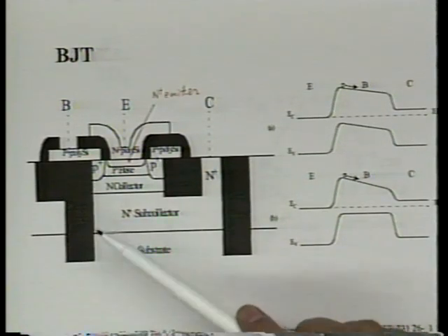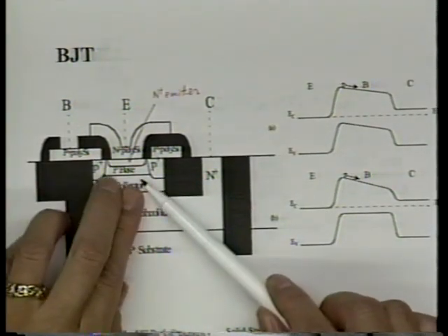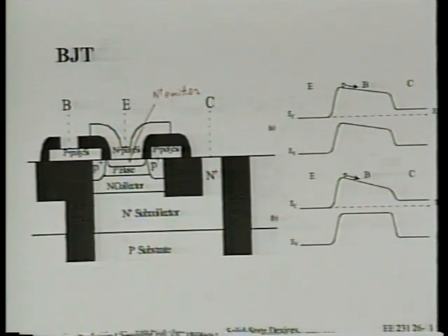Not only because we have a heavily doped N junction and quite heavily doped P junction, which make the base-collector junction breakdown voltage low, but also because of something we talked about in connection with snapback breakdown of MOS transistors. Do you remember what that is?